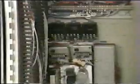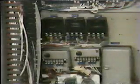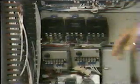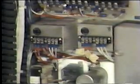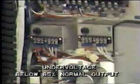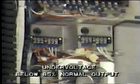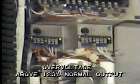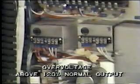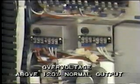The under voltage relay Z266 and the over voltage relay Z268 are located inside the console, beneath the governor. The under voltage relay will shut the engine down if the generator's output falls below 85%. The set point, however, can be adjusted between 85 and 120 volts AC. The over voltage relay will shut the engine down if the generator's output increases to more than 120% of normal generator output.